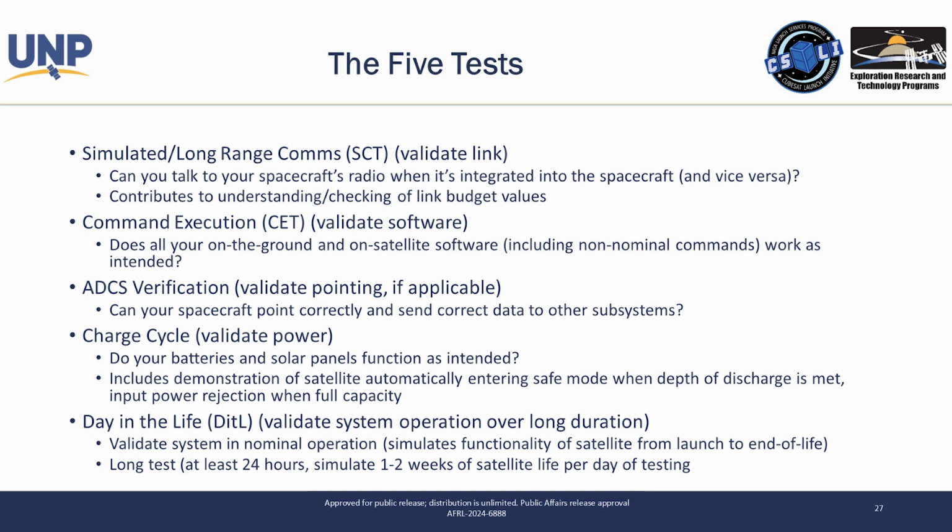The command execution validates that your software is capable of both running your mission and addressing faults, responding to all commands, including off-nominal ones, and that they have the desired effect. ADCS verification proves that you can, if you have to, point your satellite where you want it to point, and that it can actually tell you that, so you know that your camera is aimed at Zimbabwe and not deep space because it's upside down.